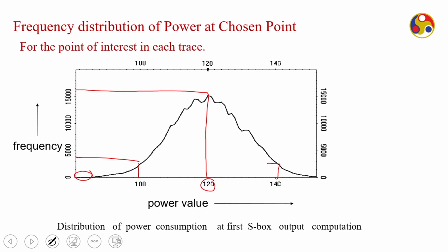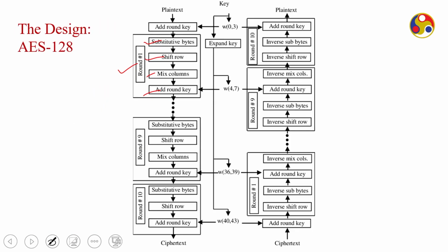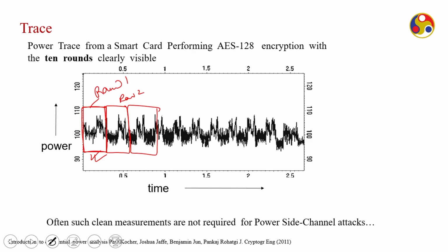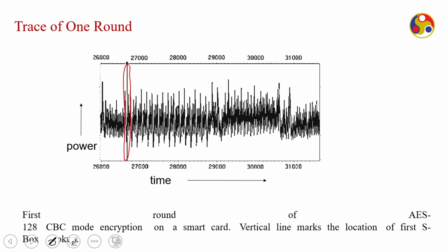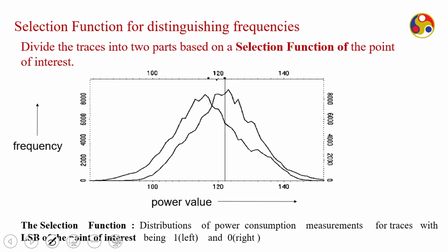So, you have the plain text, which is basically XORed with the key in this add round key, and this is your cipher text, right. If I have this cipher text, say I pick one of the bits of it, it is basically 8 bit, right. Let us say I take one bit of them and I will see what happens. I will run again for 10,000 or 20,000 plain texts, but I will fix, let us say, the LSB of that byte, right.